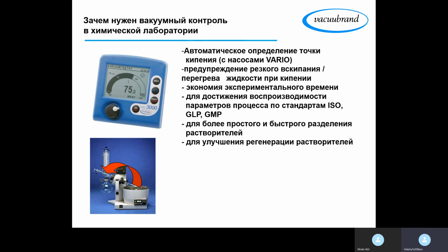But let's imagine that your solvent starts to boil at 100 millibars. At the moment X minus 1, for example at the 10th second, we have 150 millibars, right? Then the pump pumps again. It measures the vacuum. It reaches 100 millibars. Then, at 100 millibars, the solvent starts to boil.